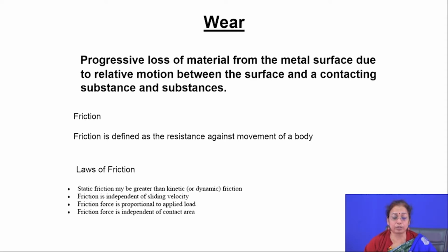If you talk about the different factors responsible for the wear properties of a material, it is mainly hardness, to some extent toughness of the material, and coefficient of friction as well. With coefficient of friction, surface energy comes into picture.